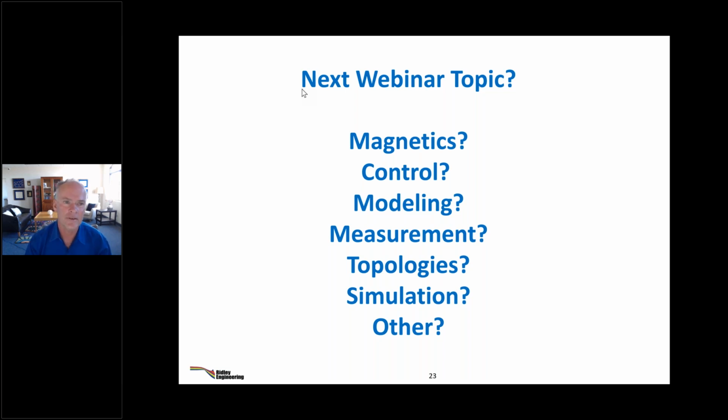Control is more complex, such that most of the applications we see go to digital control. Do you want to go there? Do you want your life to be easier? So automotive industry, you should certainly be looking at LLC, but if you can get by with a buck and a boost, use a buck and a boost. Life is easy, and you want it to be solid and rugged and easy.